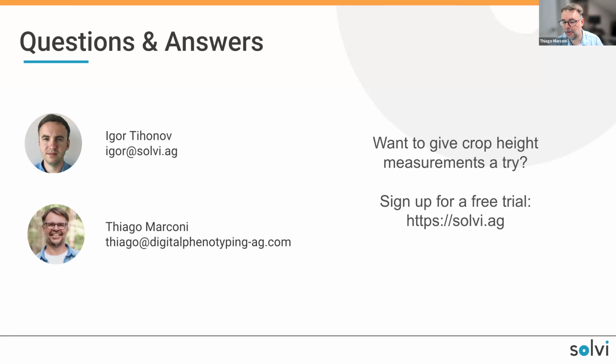Like Igor mentioned before on one of the questions, changing the angle of the camera can help in photogrammetry to measure height, as well as your mapping pattern. Looking at a grid pattern of mapping also increases the number of pictures that you're taking, basically the area, and you get more accurate heights and volumes of the object that you're trying to measure.